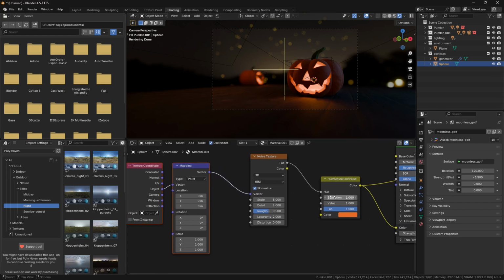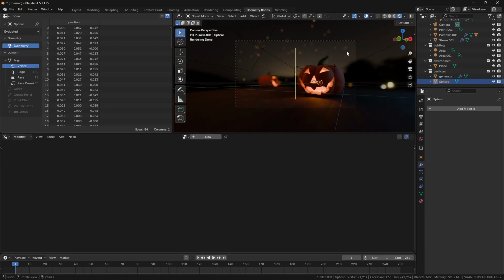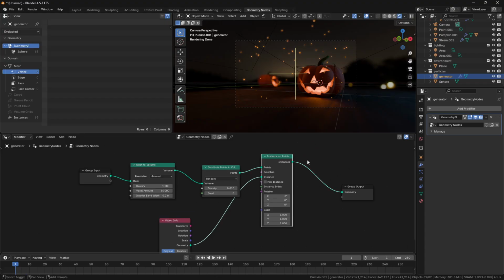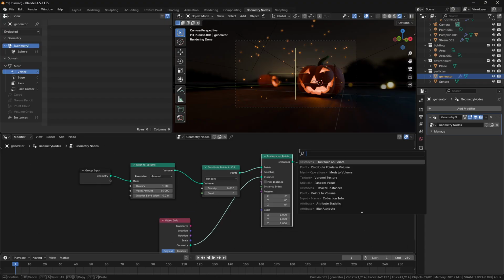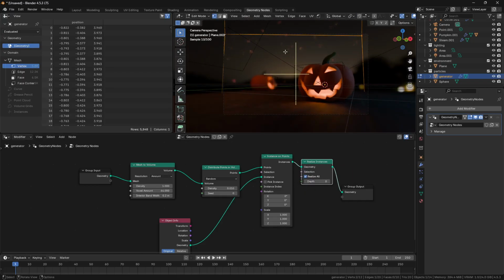So let's have a look and scale it here. Can we have something interesting? Yes, I know why it doesn't work. We have to come back to the geometry nodes again here, and we have to realize instances, or it will not work. So let's search for realize instance here, and we start to see some variations.